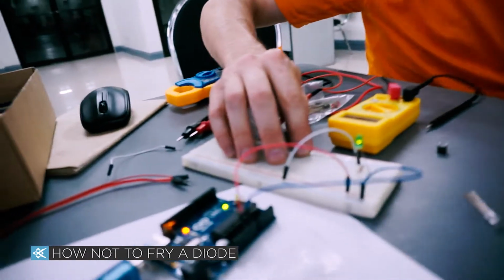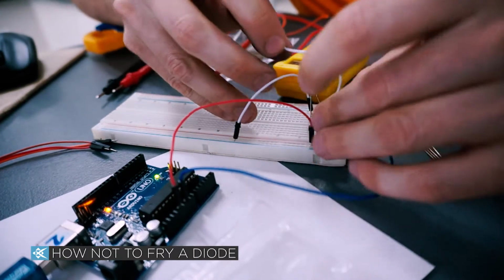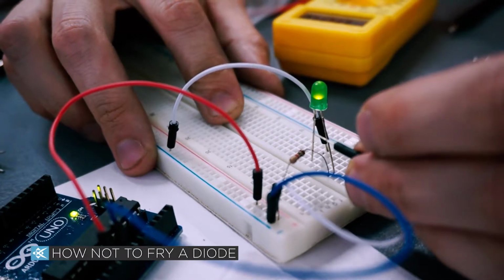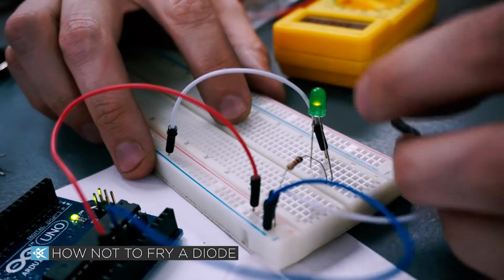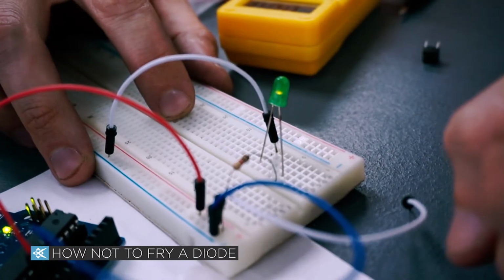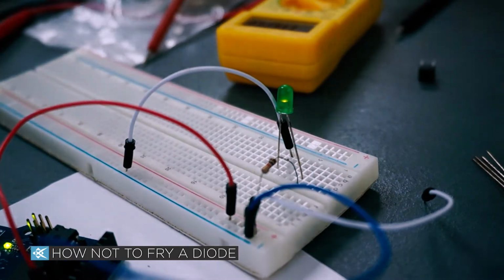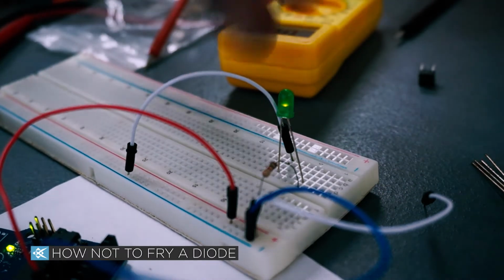And if you don't put a resistance there, if you bypass the resistance, you're going to see that LED become really strong and then even fry quite quickly. It's already dimmed now because I've fried part of it. So it's actually not happy anymore, because you put so much current through it and it's not supposed to do that. If I leave it there, it will stop working.